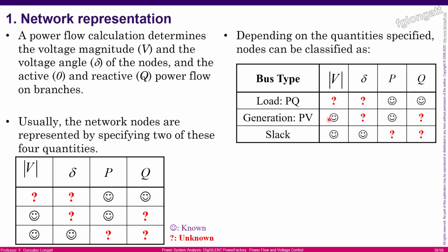Okay? One of the things about the PV bus bar is that the reactive power in this case is used to keep this voltage constant. Okay, I will discuss more about voltage regulation and the effects of those limits on the generators in the practical case. Okay, but coming back to the slack bus bar, as you define two parameters, magnitude and angle, for the voltage, the unknown